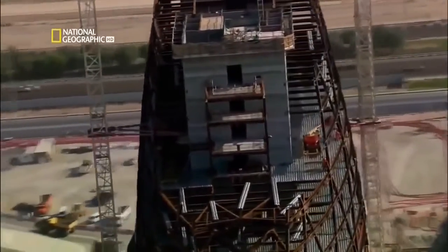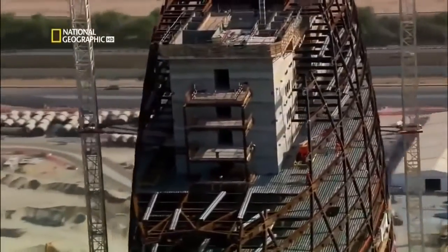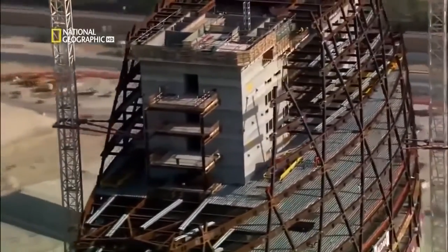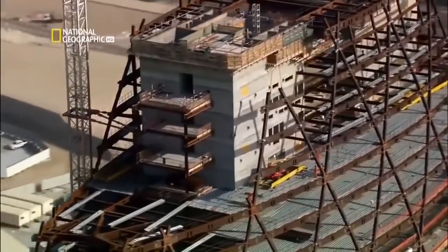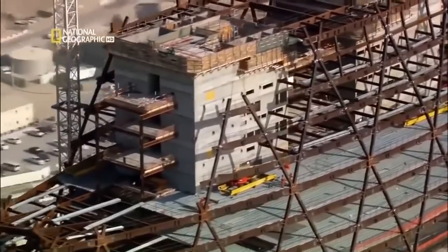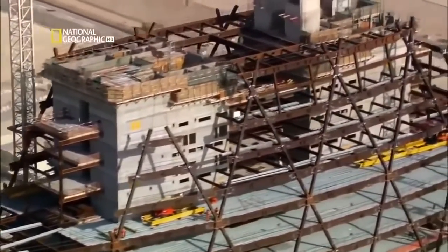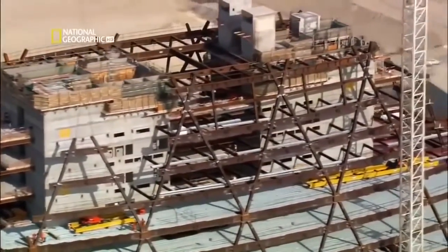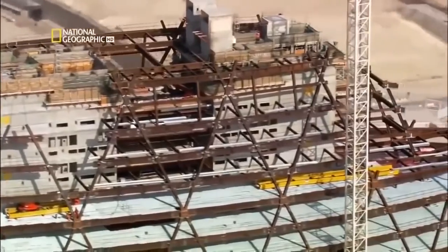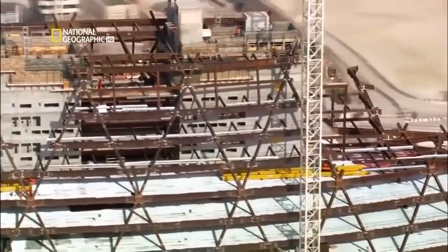Due to unforeseen circumstances, the completion of the outer skin construction has been put on hold, and the team noticed that the steel framing has begun to creep. With such a complex structure, even the slightest movement of a few millimeters could mean the remaining sections of the frame won't fit together.